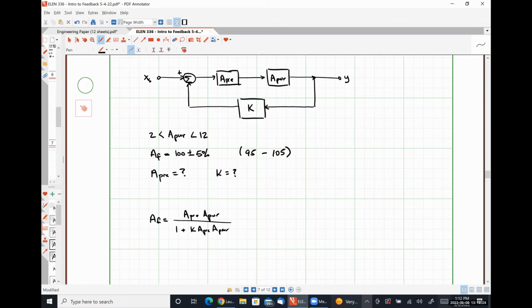So it effectively behaves exactly like we would expect the feedback system to do, where we're just lumping together these two open loop gains, or multiplying them together to get the overall open loop gain of our system, much like we treated cascaded amplifiers in circuits 2.